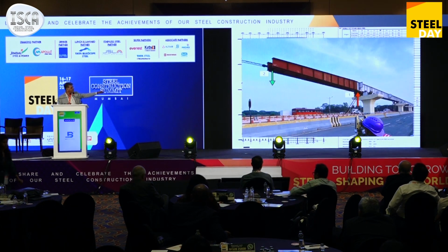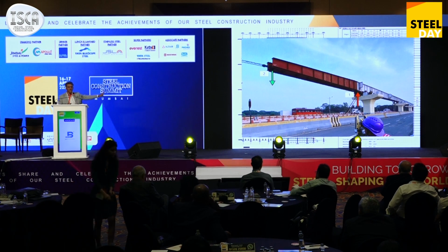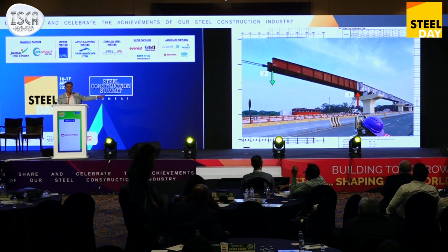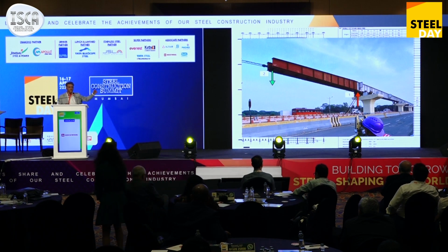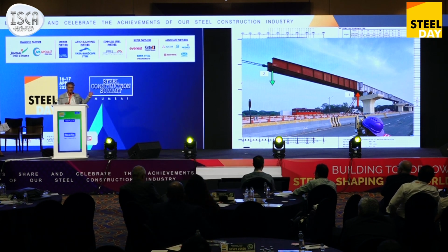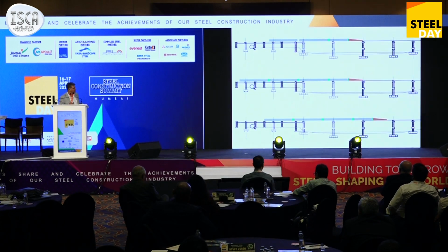During launching, we confirmed that the deflection at point number 2 and the maximum reaction at point number 1 matched all the design stages. We also confirmed with the surveyor during the entire launching. The expected deflection was around 25 mm, and what we got was around 12 to 13 mm under the maximum load condition.